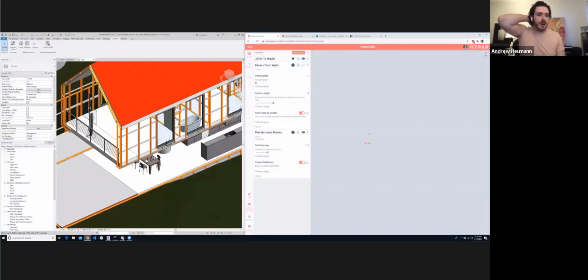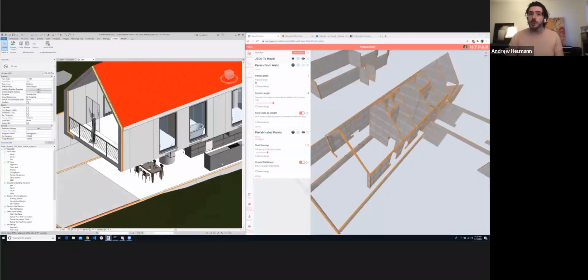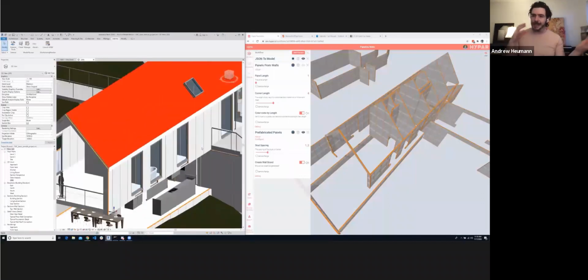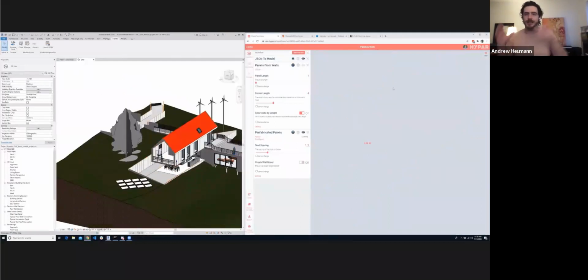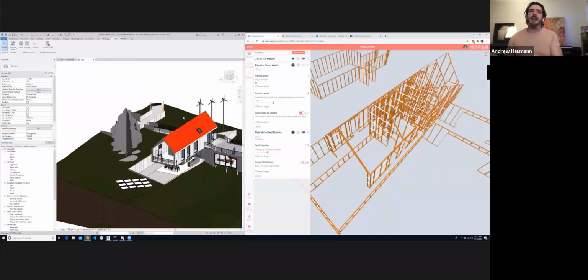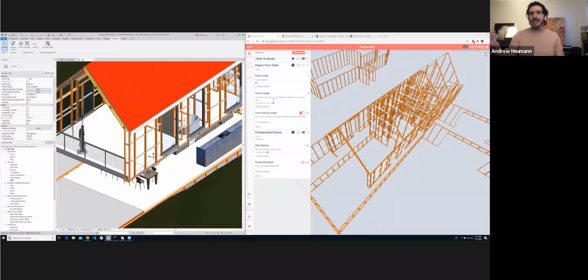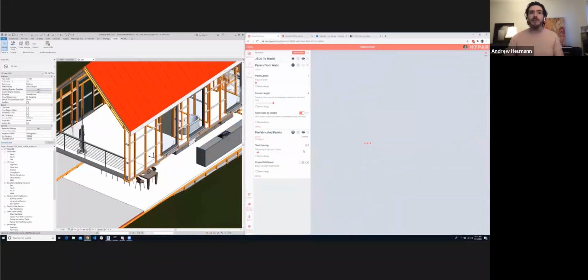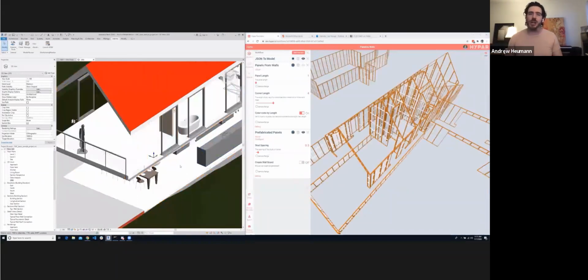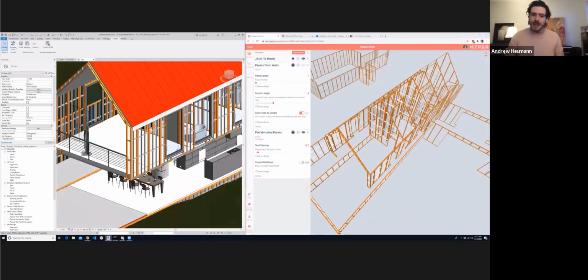Finally, we also know that for Hypar to be a practical tool for people to be able to use it today, you'll have to be able to use it in context with your existing tools. So we've enabled translations to and from Revit elements and Hypar elements. So you can take your Revit model, stream it into Hypar, do stuff with it, and stream those results right back. So you can see this is actually a function or a workflow operating live, and it's streaming its results back into Revit. So if I make a change in Hypar, I can visualize that result in Revit dynamically. And this is sort of a preview mode, but there's also a way to basically bake that geometry back into Revit as well as real native elements.